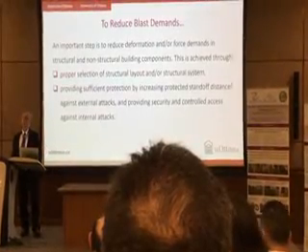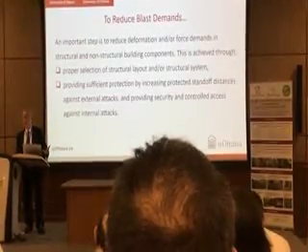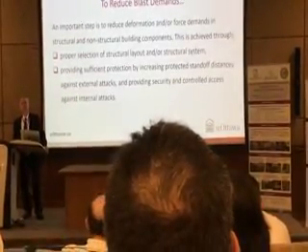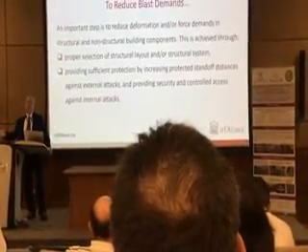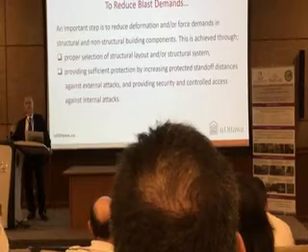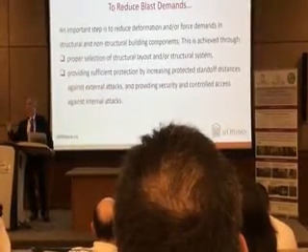In earthquake engineering, we strengthen buildings. In blast engineering, we harden buildings. It's the same as strengthening buildings. But those are hard measures. We increase column size, we wrap them with FRP, we use different materials to protect them. Those are hardcore engineering measures.